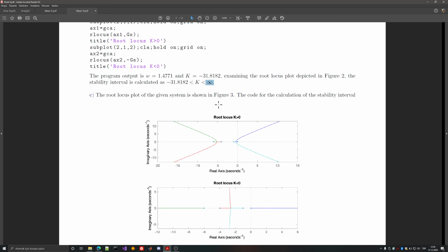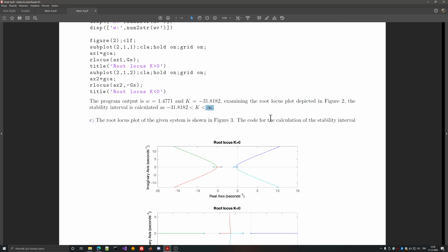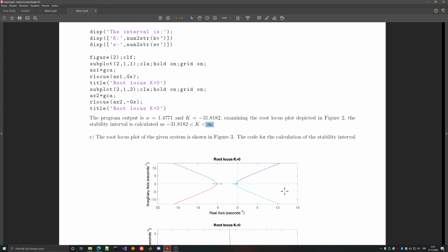So the higher the degree, the lesser the angle here. So it will be more likely that the poles try to cross on the right half plane. So adding one more pole creates this interesting structure where both of them are crossing, so that they will become unstable.